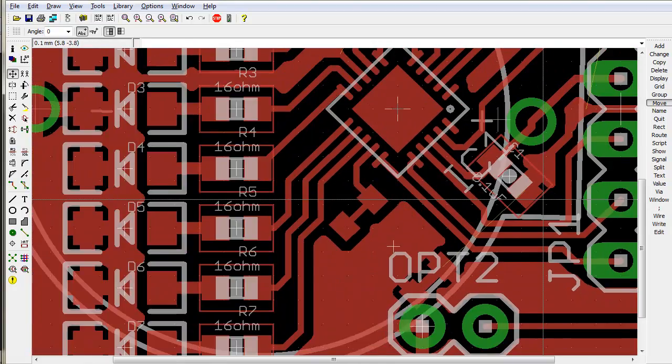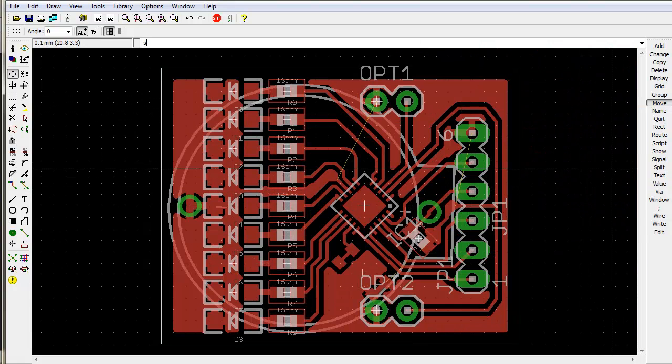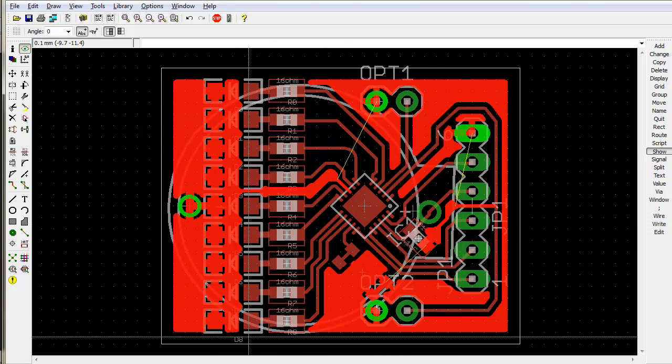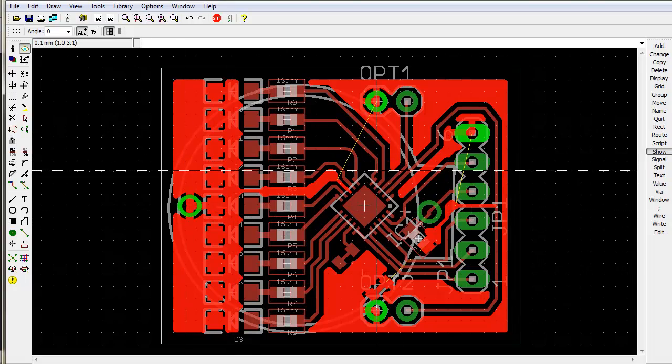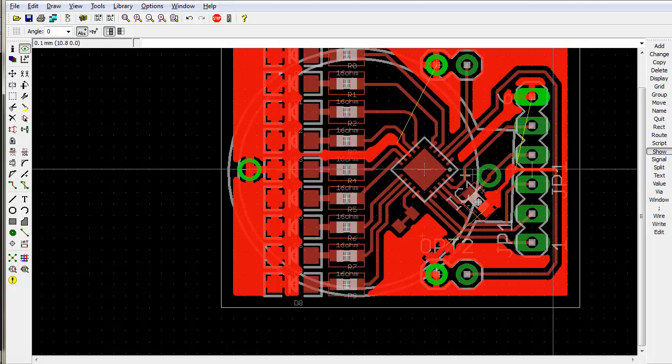We're still missing one. Where's that guy coming from? So let's take a look. Show ground. We're looking for the yellow wires, which are the unrouted wires. And we can see this piece here hasn't joined, which is where we really need it because that's where the main power comes in. And this one isn't connected to this one because the wire is in the way.